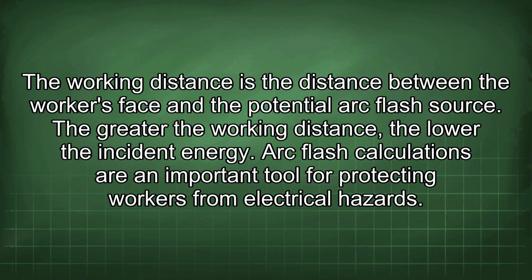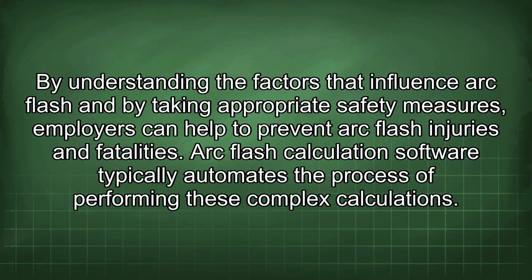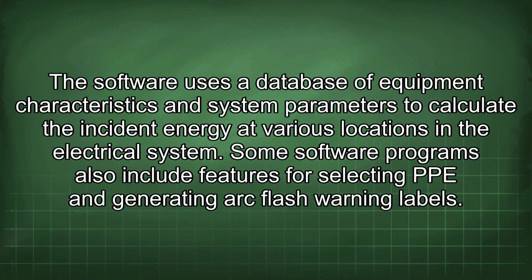Arc flash calculations are an important tool for protecting workers from electrical hazards. By understanding the factors that influence arc flash and by taking appropriate safety measures, employers can help to prevent arc flash injuries and fatalities. Arc flash calculation software typically automates the process of performing these complex calculations. This software uses a database of equipment characteristics and system parameters to calculate the incident energy of various locations in the electrical system.